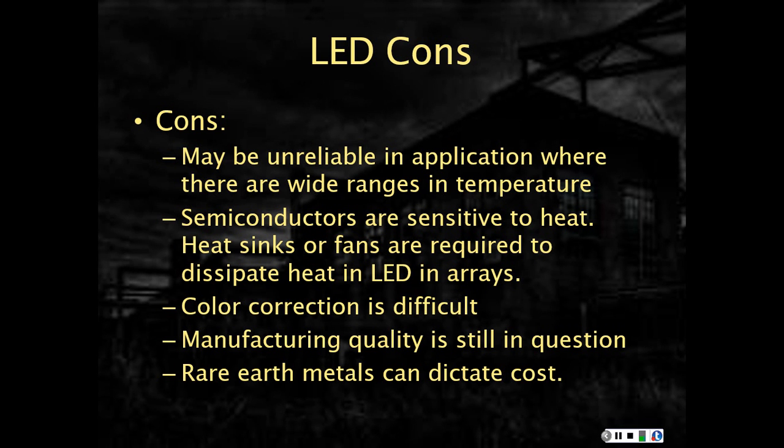The minute you do this, they give off a lot of heat. So LEDs that are put in an array have to have some method to dissipate the heat. Either they have to add some sort of highly conductive metal to draw the heat away, like fins, or they have to put little tiny fans in. Both of these things have a tendency to reduce the overall efficacy of the lamp, especially if they have little fans.